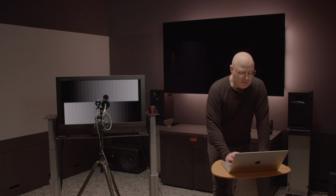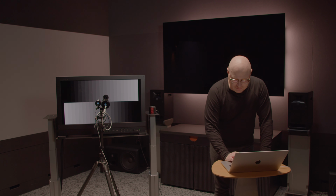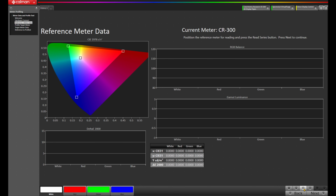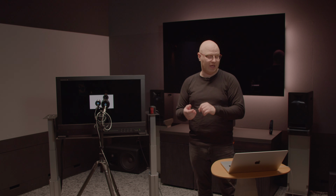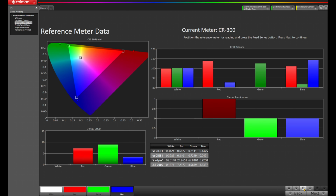Let's press Next. The next step in the meter profiling workflow is to take reference meter data. This is going to be used later to correlate to our profiled meter to see how accurate the profile came out. Let's choose our reference meter by selecting the Meters tab. Choose the CR300, come down to the bottom right and press Read Series. At this point, Calman's going to put up a patch, take a reading, and plot the data. It's going to go through white, red, green, and blue. Okay, now that our reference meter data has been collected, let's press Next.